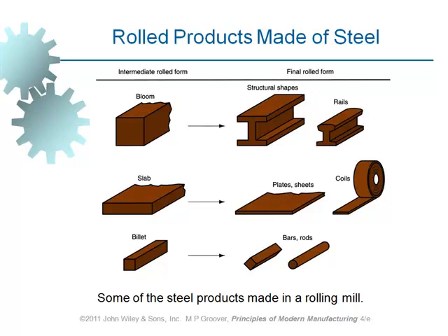As I said, when this material is subjected to rolling, it is often stronger. Even if we make use of hot rolling, which is at elevated temperature, still we get a desired orientation for the grains which are present in the crystal structure of the material.